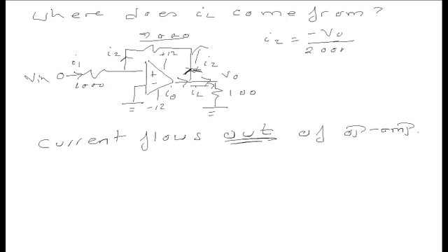Part 1. Part 2, when you're looking at an op-amp circuit, if you already know what the gain is, don't do the analysis again. Replace the op-amp with its gain.